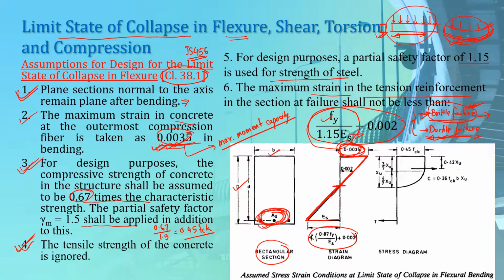So in our code, in the limit on this maximum strain, this first term corresponds to the strain at the yield stress, that means Fy, for the case of mild steel and other types of steel bar which have a well-defined yield point. So for mild steel or any other type of steel which has a well-defined or fixed value of Fy, this is the value of limiting strain or the maximum strain.